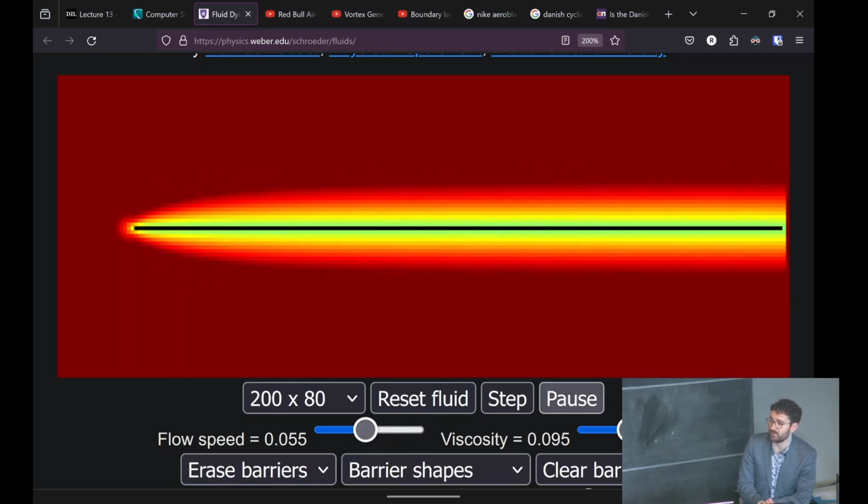This simulation also allows us to adjust the viscosity. Now viscosity is on the bottom of the Reynolds number. So what do we expect as I raise the viscosity? What will happen to the boundary layer thickness? It gets thicker, right? This makes sense. Like if you have a really thick fluid, you expect a big region of kind of viscous flow near the boundary. So if I raise that, hopefully you can see that the boundary layer gets thicker as I increase mu.